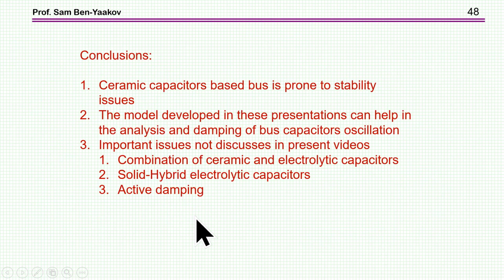So let me just wrap up here with some major points that we've shown here. We've shown that ceramic capacitors are really causing some instability, and that the model developed in this presentation can help, I think, the analysis and damping of the bus capacitor oscillation.